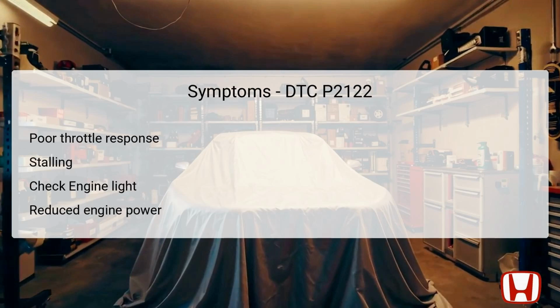Symptoms associated with DTC P2122 can include poor throttle response, where the vehicle hesitates or lacks the expected acceleration when the pedal is pressed. In more severe cases, the engine might stall unexpectedly, particularly during deceleration or idle.